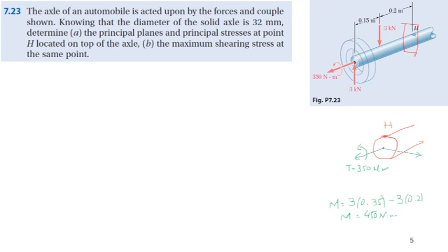And the direction, so the direction will be like this. Okay, let me put negative over here, positive over here, clockwise and counterclockwise direction. So minus, as this direction is showing in this way. Means now due to this bending moment at H, the top surface will be under compression.